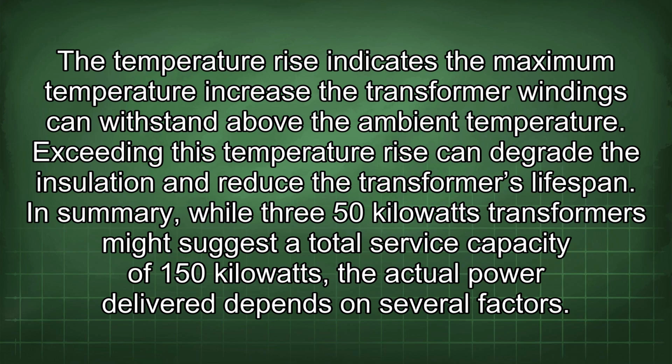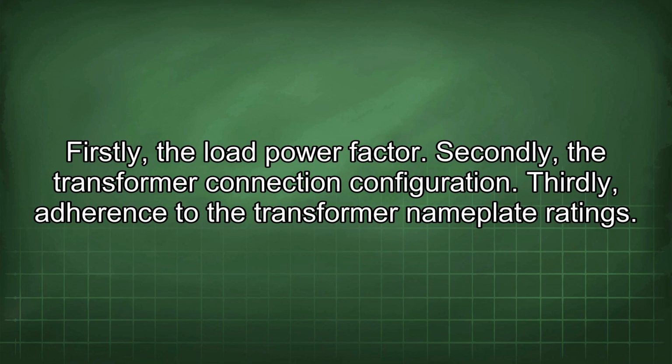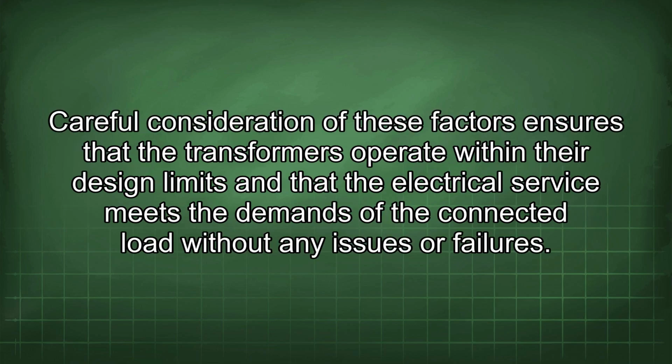In summary, while three 50 kW transformers might suggest a total service capacity of 150 kW, the actual power delivered depends on several factors. Firstly, the load power factor. Secondly, the transformer connection configuration. Thirdly, adherence to the transformer nameplate ratings. Careful consideration of these factors ensures that the transformers operate within their design limits and that the electrical service meets the demands of the connected load without any issues or failures.